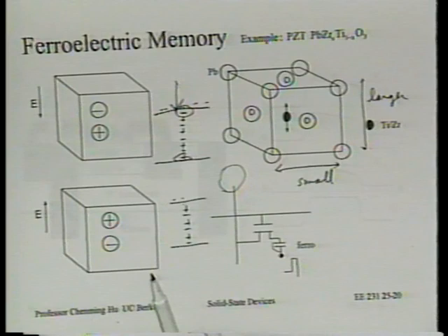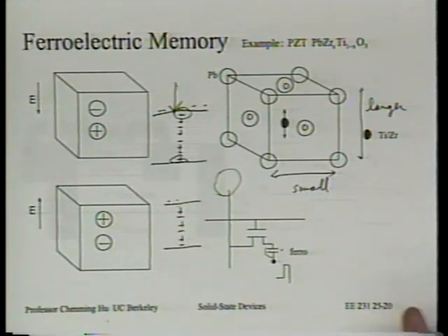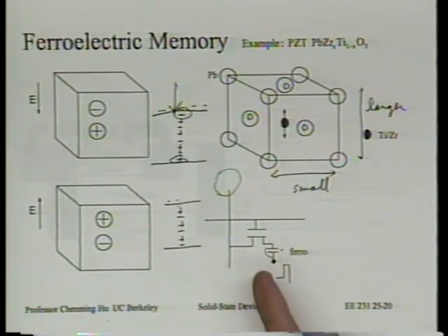You see what I'm saying? Charge on the bit line, then we can tell whether it's polarization 1 that's stored here, or polarization 2 that's stored here. You follow that? Okay. And you can also be non-volatile, because if for some reason the power is lost, years later, you can still read it. It's still there. The way it left, the polarization is still there.